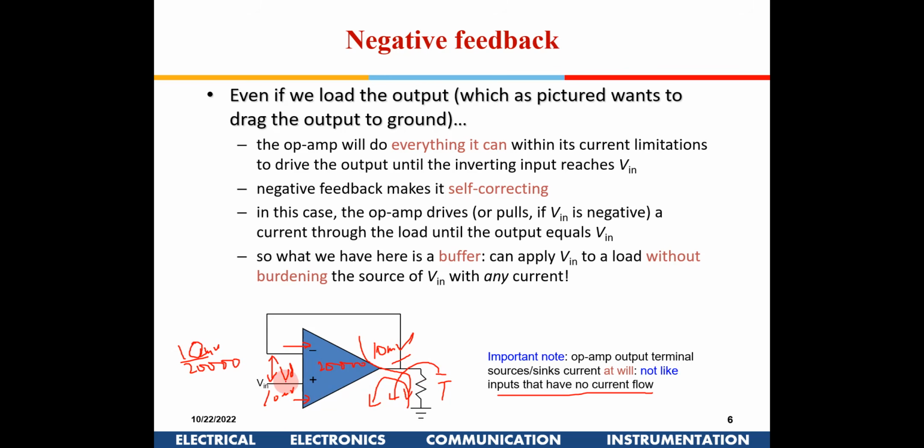But it will not affect the input voltage. The input is isolated from the output, so these currents come from the power supplies. Like we learnt about the differential amplifier, we are not drawing any current from the input, because the inputs see the gates of the transistors, which is almost like an open circuit. So the output currents will be from the power supplies.